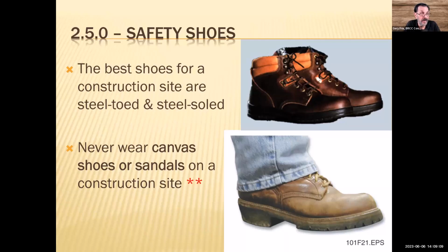The trouble with steel-soled shoes or boots is they're harder to walk around on because they don't flex as much. So most of the steel-toe boots that you buy at a lot of stores, a lot of the common and affordable ones, have no protection for the bottom of your foot. So just realize if you're on terrain and job sites where there can be nails poking up, or sharp objects like rebar sticking up in mesh, which a lot of job sites are like, then you better have better protection than that.